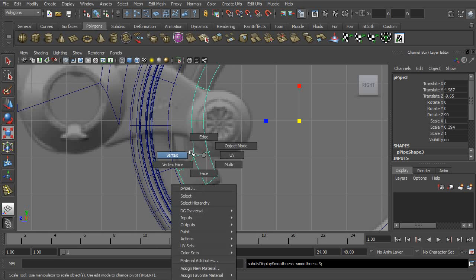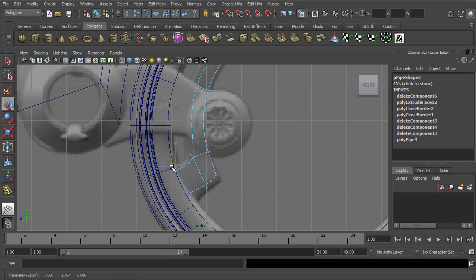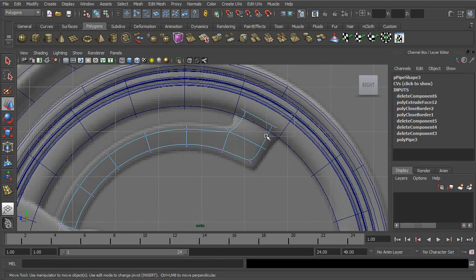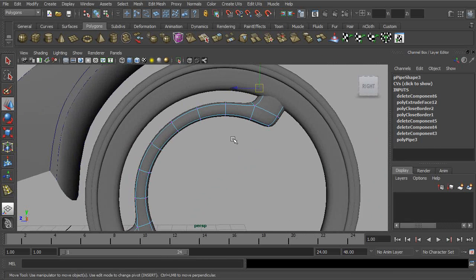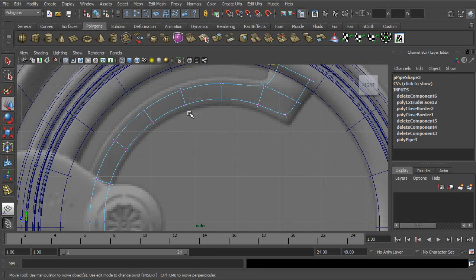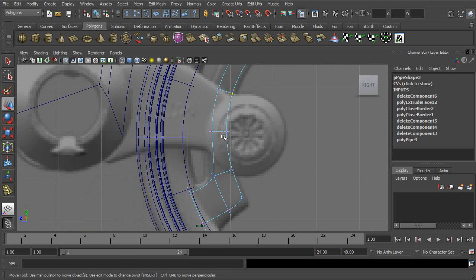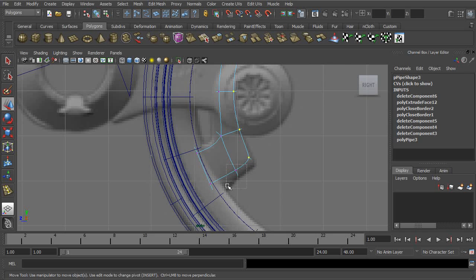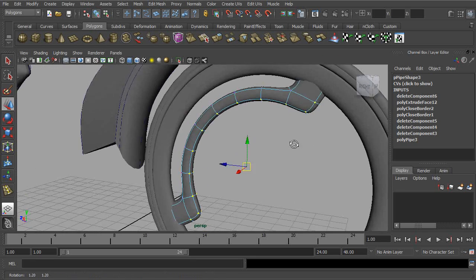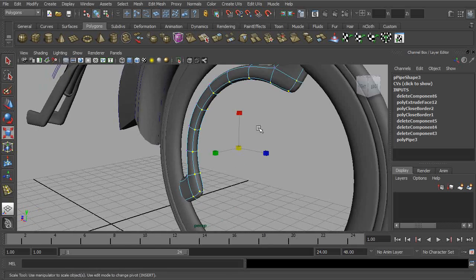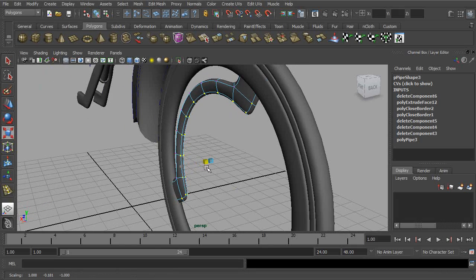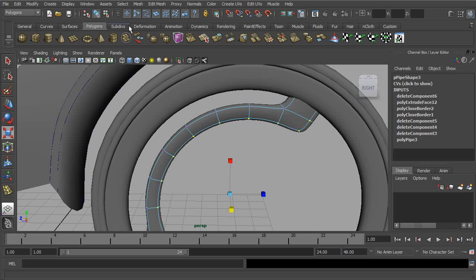I'm going to go ahead and smooth it. We can click on any of those points, make sure that they're penetrating in where they need to be. Alright, now I want to taper this a little bit, so I'm going to actually select all of the points on the outside here, or inside, I guess. And so go ahead and select all of those, and then I just want to scale them, but I only want to scale them in the Y. So we'll just scale those in to kind of sharpen things up a bit.